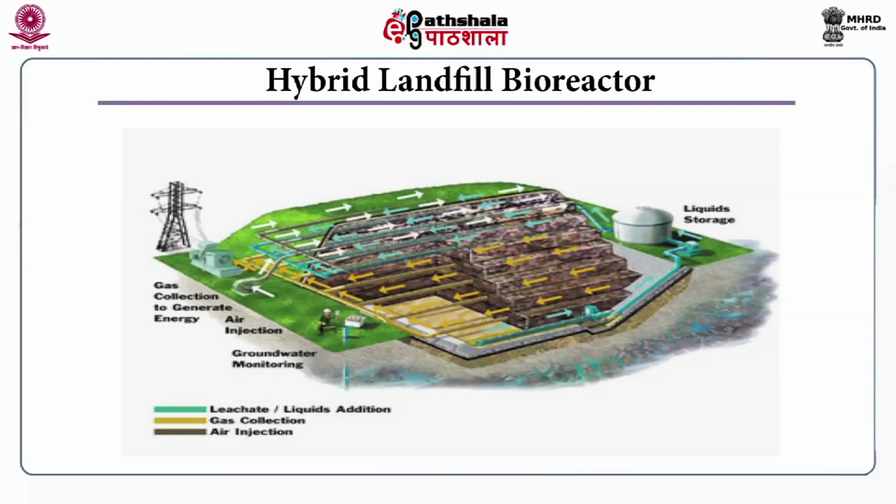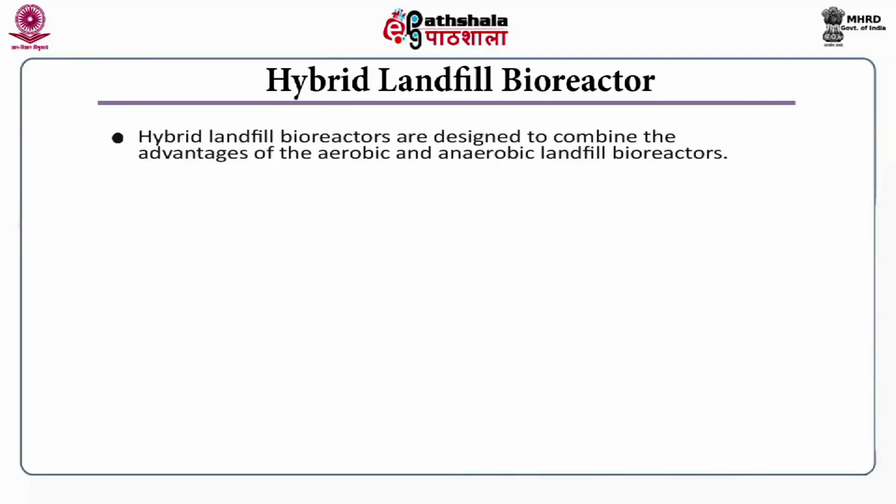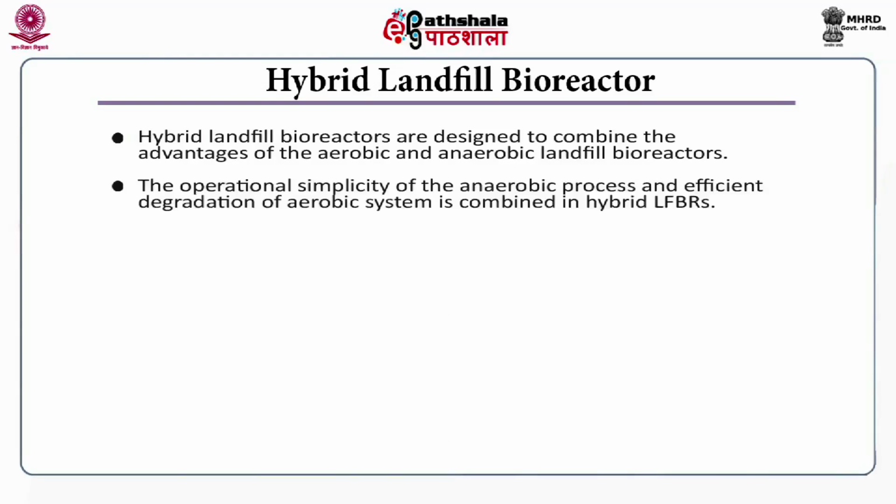The third type of landfill bioreactor is a hybrid landfill bioreactor. In a hybrid landfill bioreactor, it is generally designed in a way so that both aerobic and anaerobic degradation occurs within the reactor. The operational simplicity of anaerobic process and efficient degradation of the aerobic system is combined in this landfill bioreactor. It is generally known as aerobic-anaerobic bioreactor landfills.